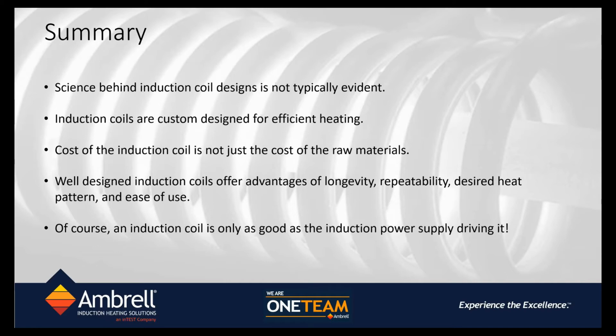Those are the only two ways I know of calculating the inductance of the coil. The capacitance in the remote workhead should have stamped values on the side, because they are pre-manufactured prefab pieces. So they are discrete values, so you can measure or read the capacitance of the box itself.